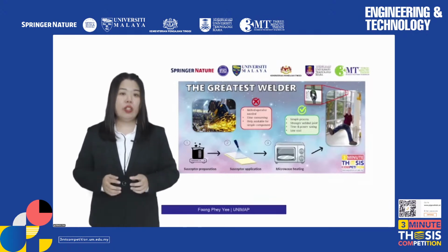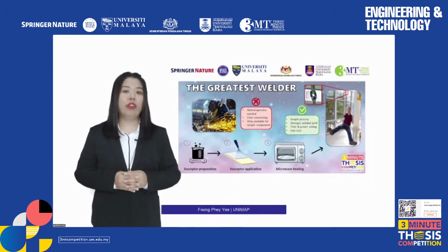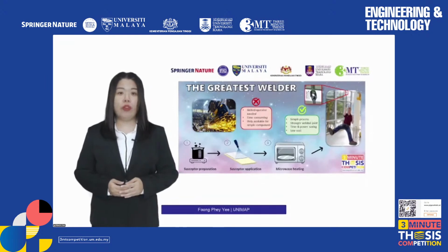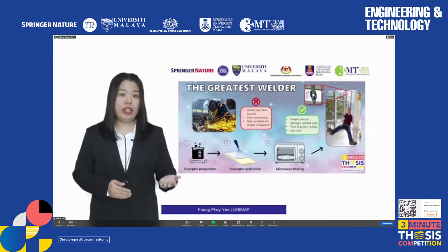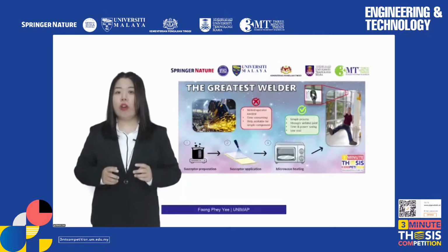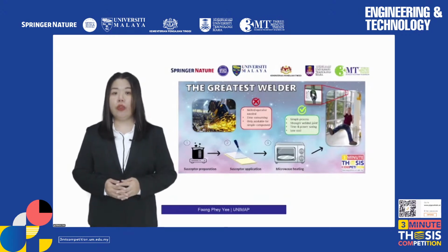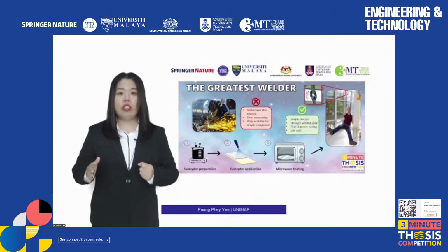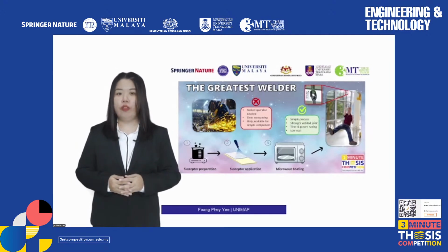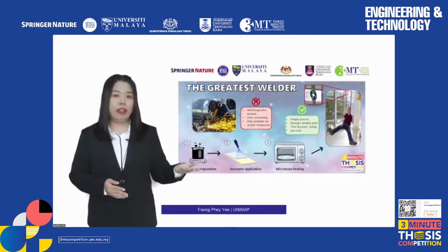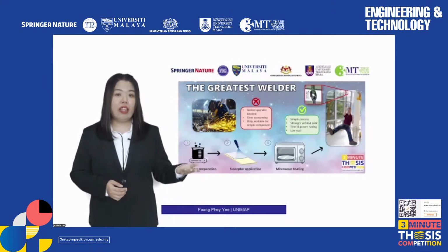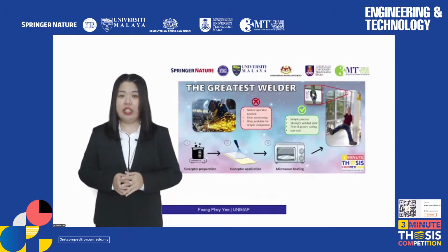Microwave welding is a welding method that works with microwave heating, like how we prepare our food in a microwave oven. For your understanding, the heating mechanism of food in a microwave oven is due to the presence of water molecules. The water molecules in the food absorb the microwave and lose part of it as heat, causing the food to heat up. It's the same for microwave welding: a susceptor material like water molecules that can efficiently absorb the microwave is needed to heat and melt the plastic.